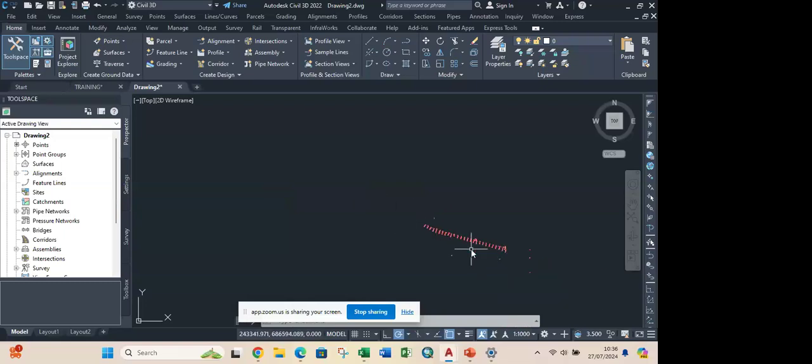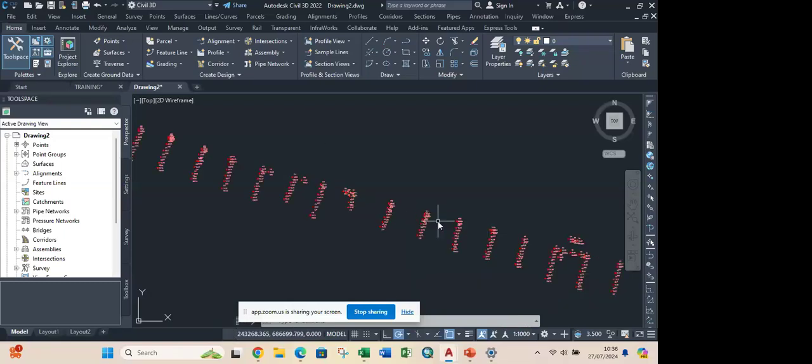So for me now, we imported the whole data. If you are working on data where the surveyor did a proper description and established a proposed center line for the road, let's say along the road he picks 5 points to the left and 5 points to the other side, that is 10 points, and goes down like that. The midpoint is taken as the center, the CL of the road, and we go like that, establishing a proposed center line.